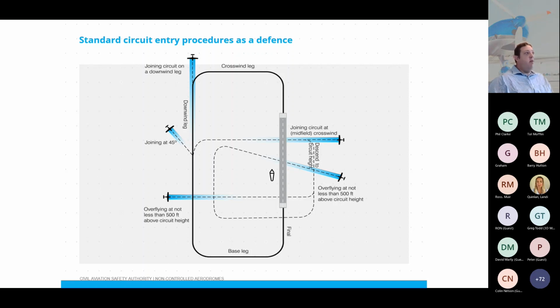So it definitely builds more time. One of the biggest issues is that you need to build an SA picture, and time is definitely something that's super critical in doing that. By overflying the airfield, you get to assess who's in the circuit, where they are located, and it gives you more time to spot them, or to ask questions to other pilots. The other thing that's important is it gives you an opportunity to assess the airfield, how busy it is. Like here at Bendigo, you can see whether the RPT is moving or taxiing, and again, assessing the windsock to make sure that the most suitable runway has been used. So there's a number of benefits to overflying the field, and in fact, that's one of the things we encourage at all times, because it's that time-based scenario that is helping increase students' situational awareness dramatically.